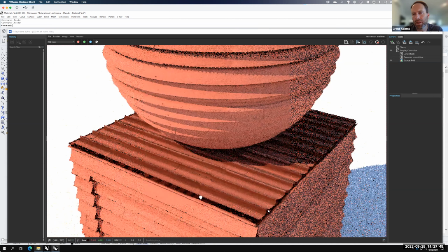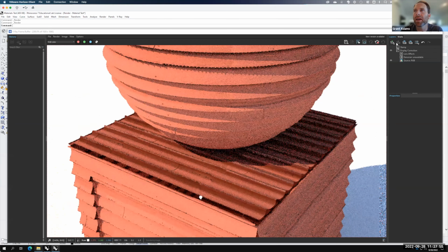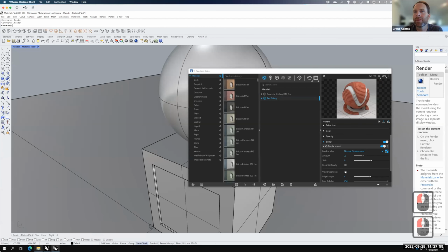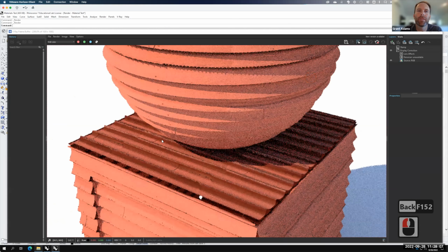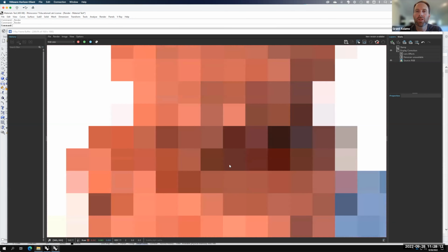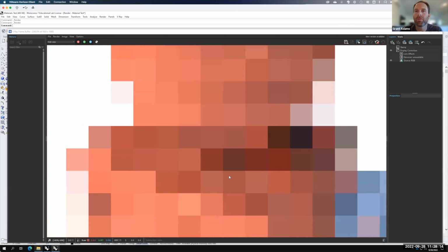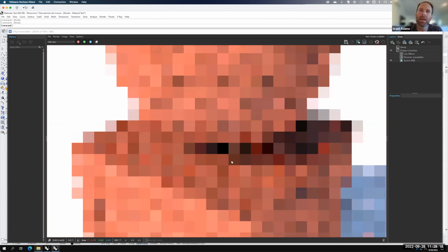And so we're getting a little bit of this slope here. Obviously, it's looking more like tiles, so my value is too high. So we'll have to stop that, and we'll have to adjust it down. So maybe 0.2, and we'll give that a shot and let it render. So we're working through this to try to create our material from scratch. So this is the loading in process that I didn't get to complete last time.